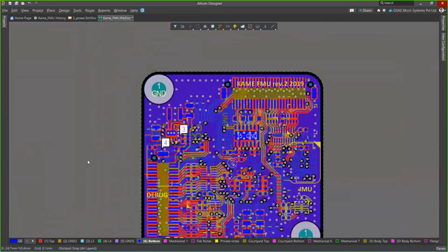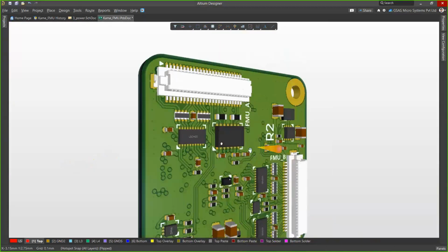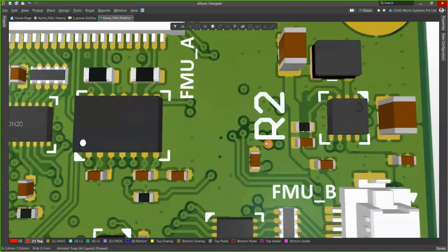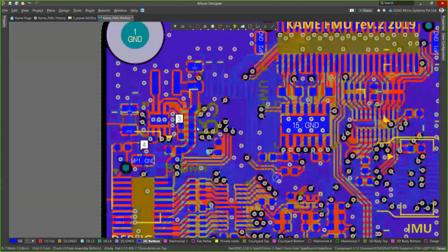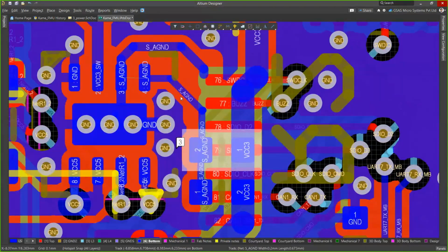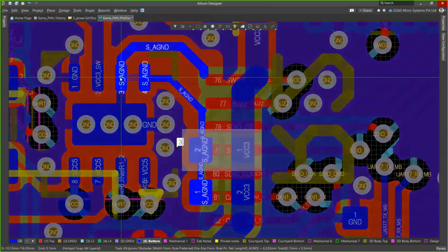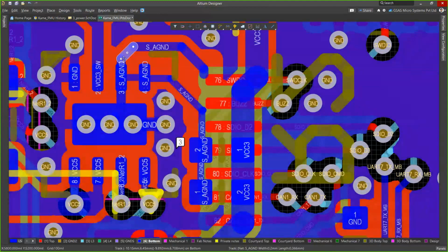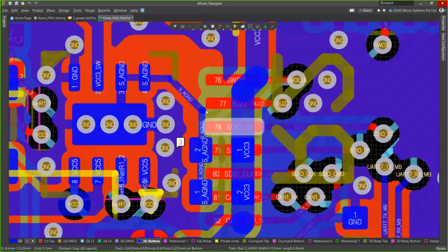I'll show you 3D. Purposely, it is being disabled for security purpose. Okay, this is R2. This is the component R2, and this is where the component has been removed in between these two. Compared here, it is showing short here. We just need to do the short, and we need to delete this tag, which is the addition of this. See, now it has been completely shorted. Sorry, something deleted, a polygon got deleted. Now it has been properly and directly connected to the ground, to the R2 resistor.